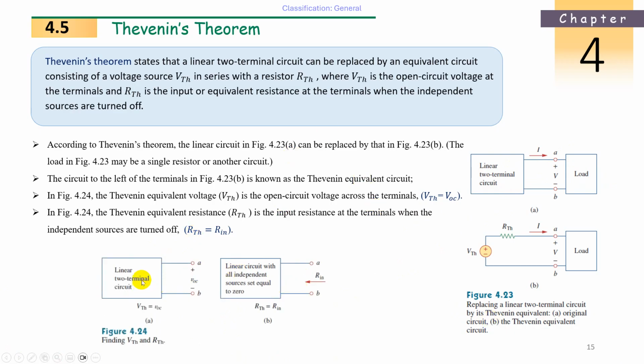Now, see here how we do it. So what is V Thevenin's? It is nothing but just removing the load resistance and, at terminals A and B, finding the VOC that comes from solving this complete circuit, big or small. That is your V Thevenin's.